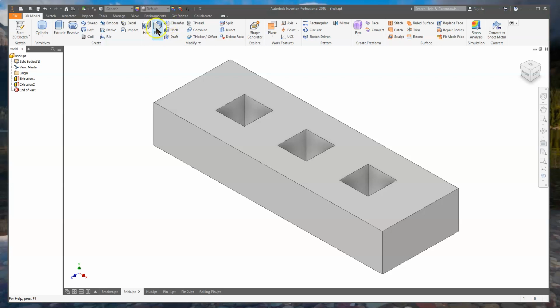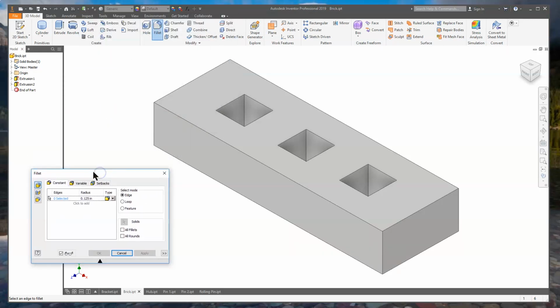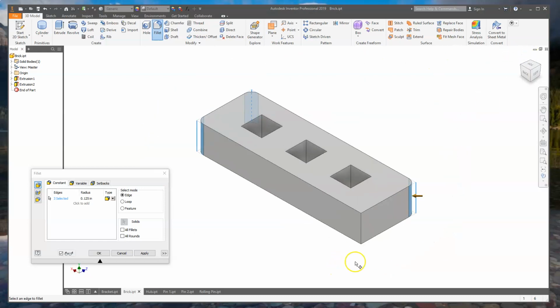And on the fillet command, I'm going to grab it off of my other screen. On the fillet command, I'm going to put down the radius. And right now, there's a 1/8 inch radius on there. So I'm going to go ahead and go, okay, that's what I want to do. I'm going to click an edge here. So it rounds that corner. I'm going to come around that back side, click on my view cube, spin it around.